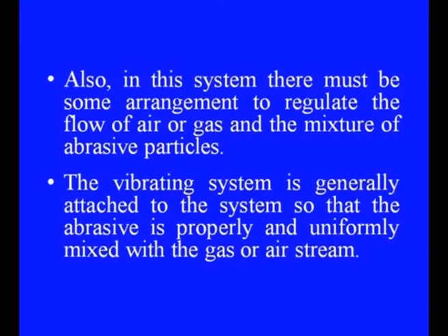Also, in this system, there must be some arrangement to regulate the flow of air or gas and the mixture of abrasive particles. A vibrating system is generally attached so that the abrasive is properly and uniformly mixed with the gas or air stream.